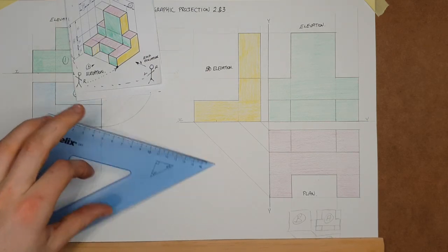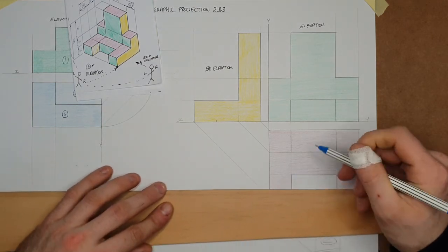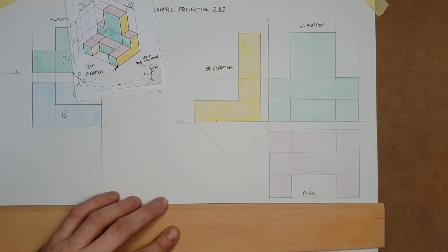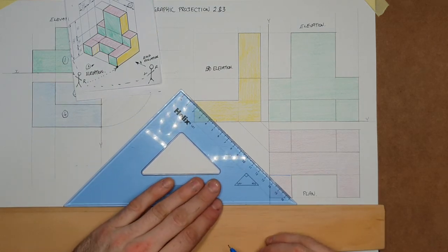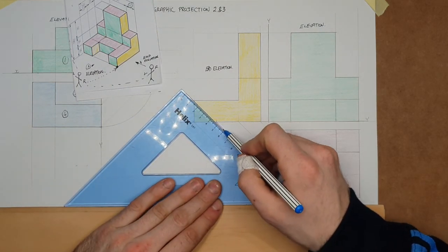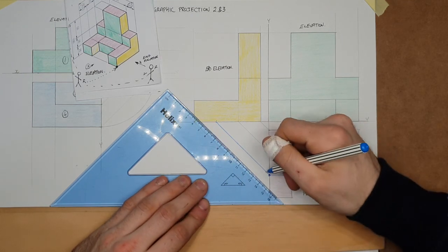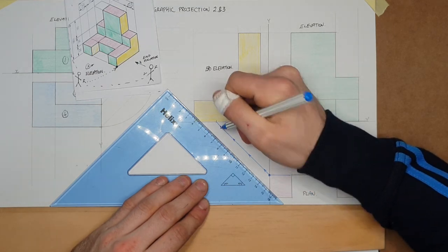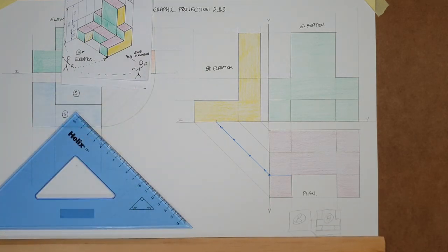Everything that is not touching the plane needs to be brought onto the plane. So this whole surface here, which is the one I'm trying to represent, needs to come onto the plane first. From the plane, it's then taken up at our 45 degrees. From here, working up, of course. And it just happens that it matches perfectly with the little 25mm mark that I had put there, which is exactly what should happen.